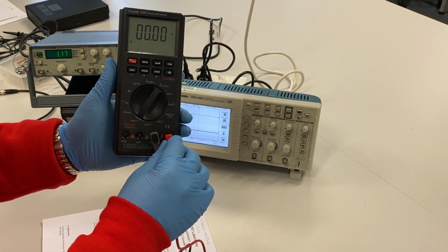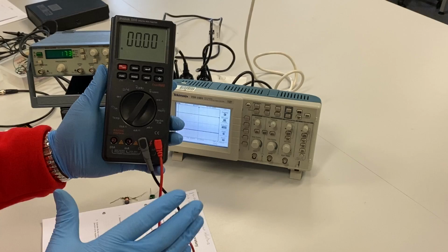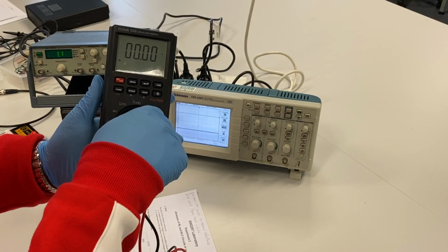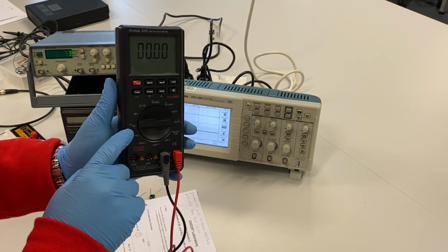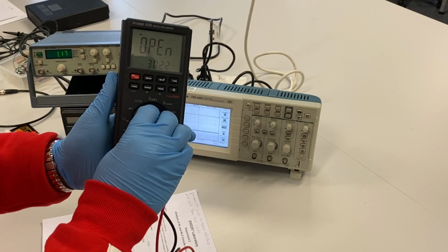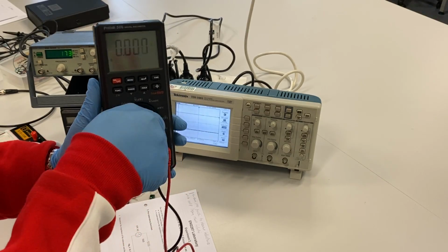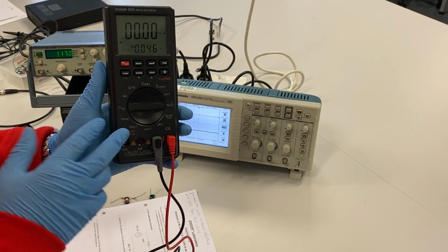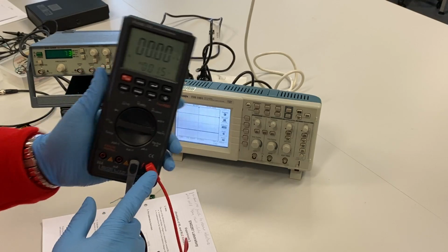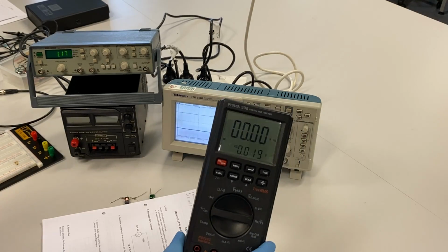But when you're measuring voltage and anything else other than current, you have to put it on the voltage side. This means if you want to measure the temperature, the capacitance or the inductance, if you want to measure the diode, whether it is operating or broken, the resistance, the voltage in decibels, the voltage, or frequency, and whatever. Everything else that you need to measure, you need to put this probe on the voltage side. This is very important. This is on this Protec 506 digital multimeter, which is one of the apparatus that we need to use.